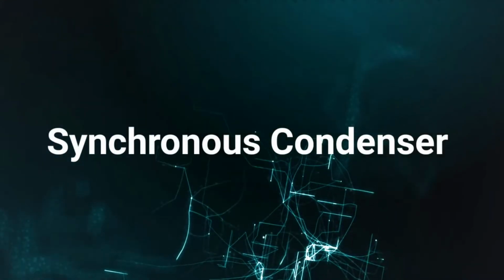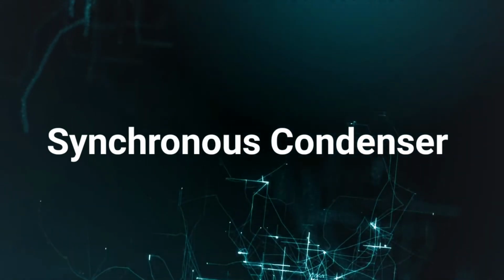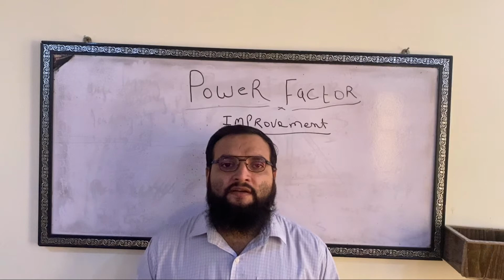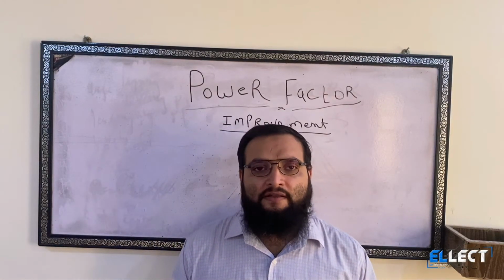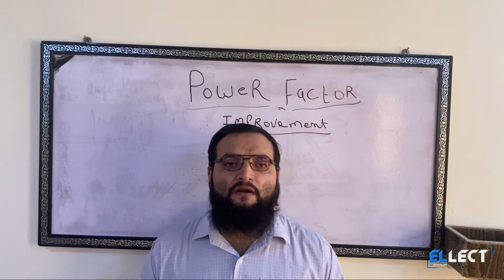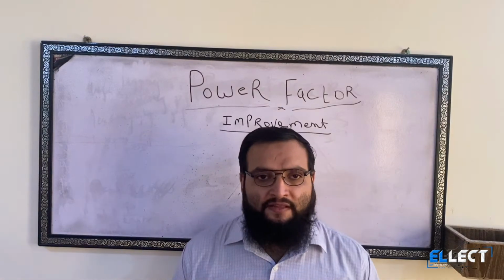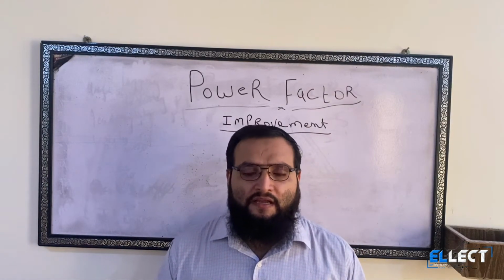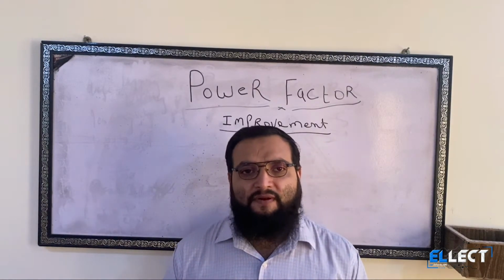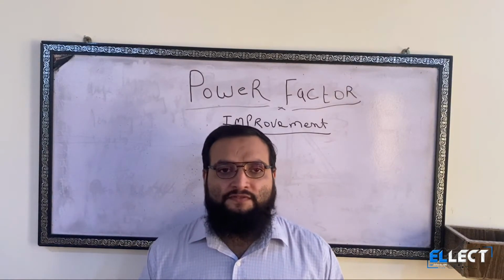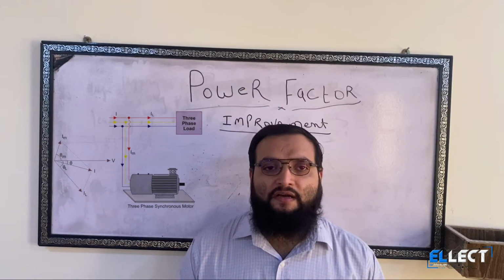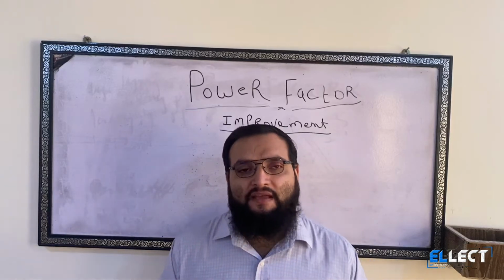Now, synchronous condenser for power factor improvement. Whenever the synchronous motor is running on low load and overexcited, it is often called the synchronous condenser. When the synchronous condenser is connected across the voltage supply in parallel, it draws the leading component of the current and works the same as a capacitor.